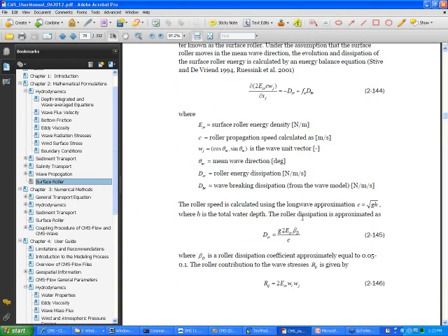It also has the effect of smoothing the wave forcing, and so it improves stability a lot. And if you look at our VNV reports that we published last year, including the surface roller makes a huge difference in the near-shore hydrodynamics, and it improves the results significantly.